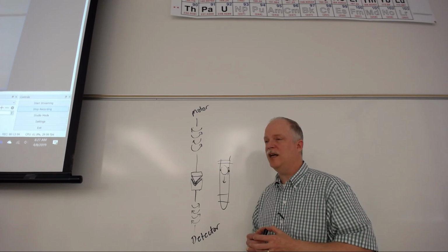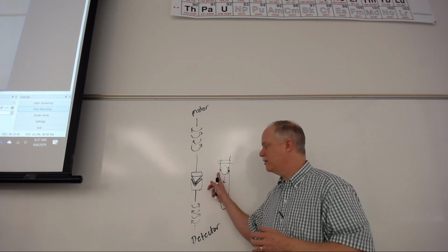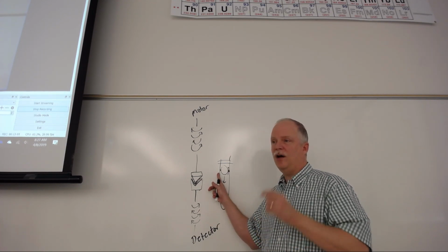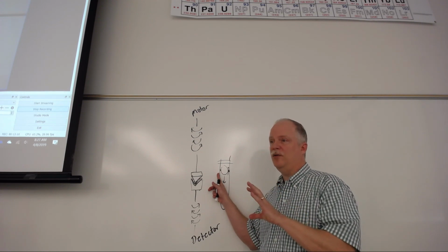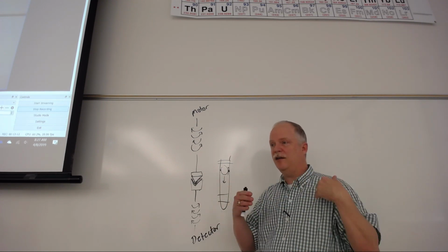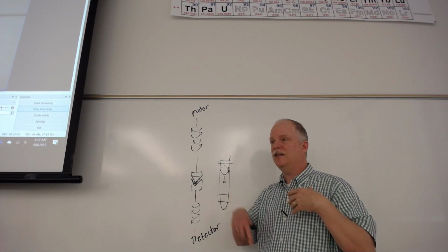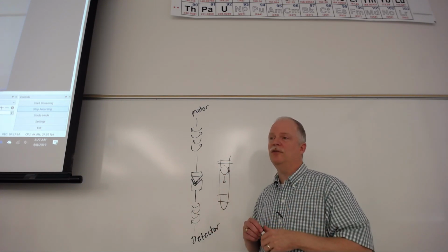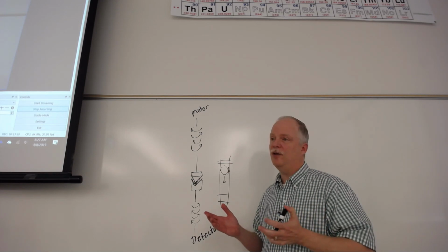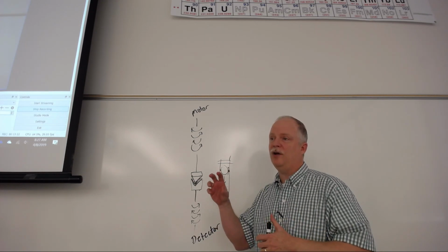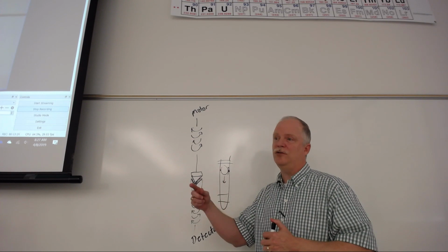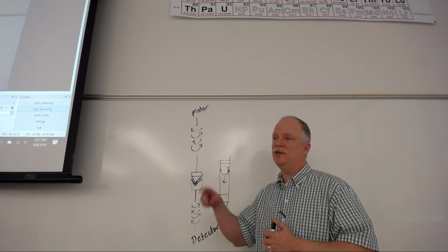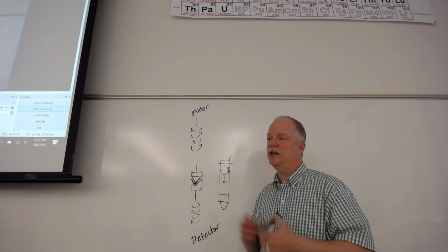It is weird, because at the surface, if that wall's not moving, then the molecules that are touching that wall are not moving. You know, somewhere between not moving and the full velocity is this laminar flow region. Now, there's also turbulent flow. We're not talking about turbulent flow. We're just talking about laminar flow. And so maybe if they had a really rough surface, you would go straight from the still surface to a turbulent flow situation. I don't know.